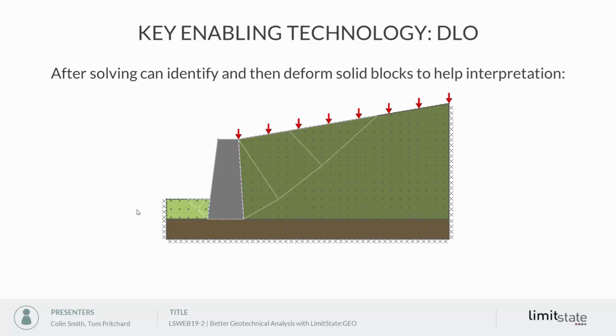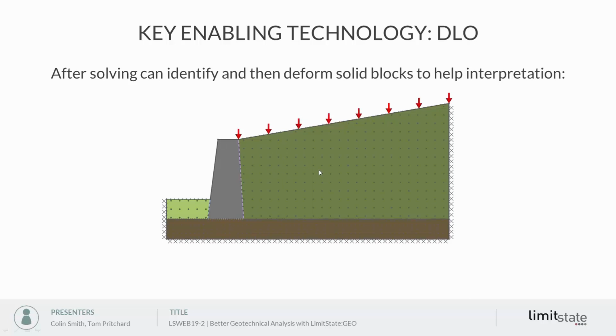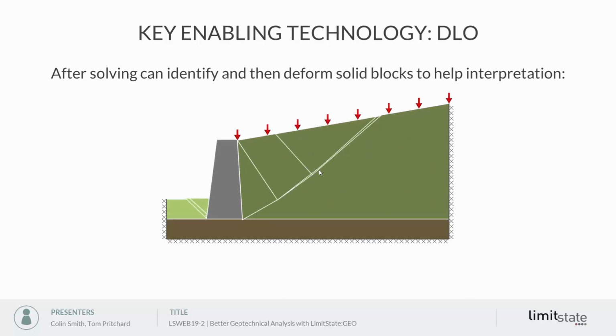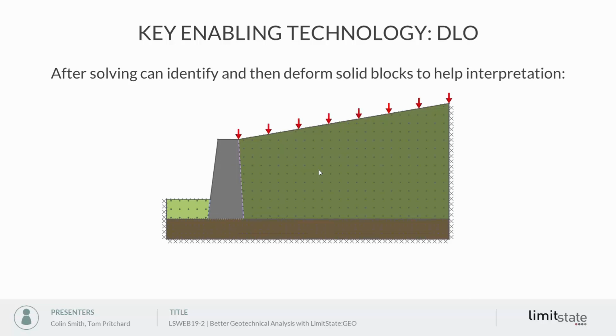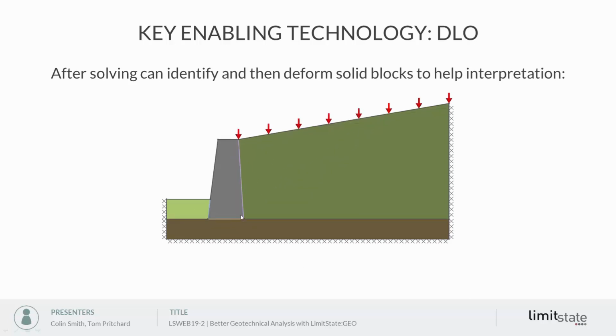So in this particular example, you can see all the nodes in this animation. We'll let it run through again, but those nodes in the background, and the software is basically exploring all those possible slip line connections, finds the critical mechanism, and then animates it to aid interpretation. That animation is strictly only valid instantaneously at the point of collapse, but we extend that to make it easy to follow, but you get some kind of anomalies like appearing down there.